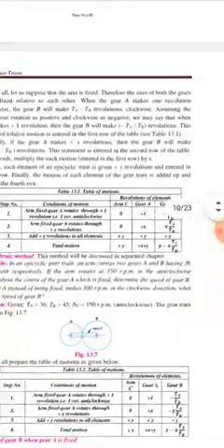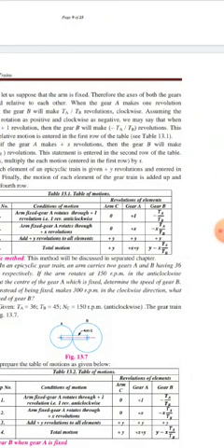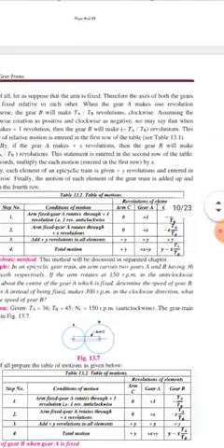So here you can see that if you give plus y revolution to the arm, then the arm rotates plus y, gear A will be plus x plus y, and gear B will rotate with minus x TA by TB plus y. So this completes the table. After that, the question can be solved according to the conditions given.